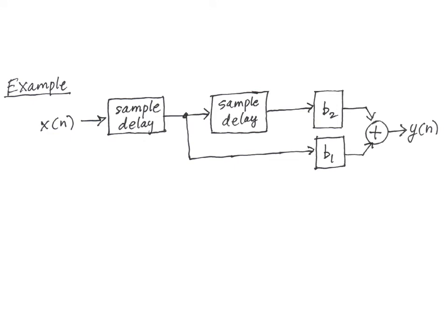Here's an example of a signal flow graph called the network diagram for a digital filter. The box following x[n] stores that sample coming in and outputs it one sample later. So what's coming out will be x[n-1].